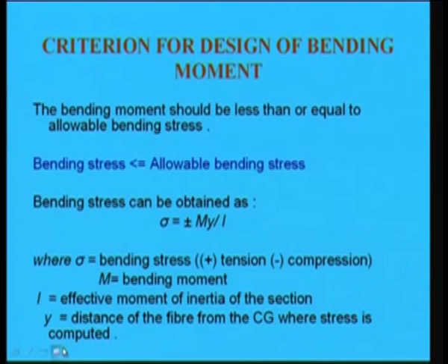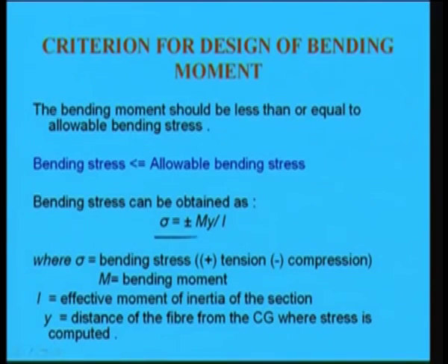Now, first we will discuss the criteria for the design for bending moment. That means, if bending moment M develops in the member, then how do we reach a particular dimension of the member, that we will try to find out from the bending moment point of view. As we know, from bending moment we can find out the bending stress, sigma is equal to plus minus M by I into y.